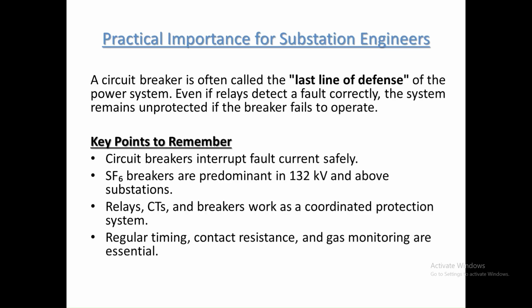So the main job of circuit breakers is to interrupt the fault current safely, and to keep the circuit breaker in operation, we should have all the relay circuitry and breakers working as a coordinated system, not as individually isolated systems. The regular timing test, contact resistance test, and gas monitoring are very much essential for healthy breaker operation.